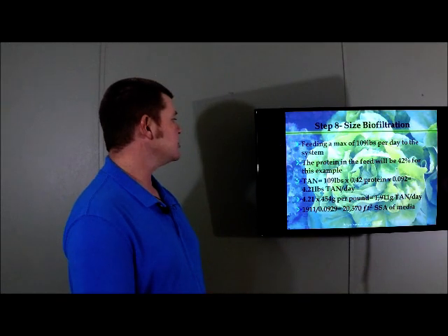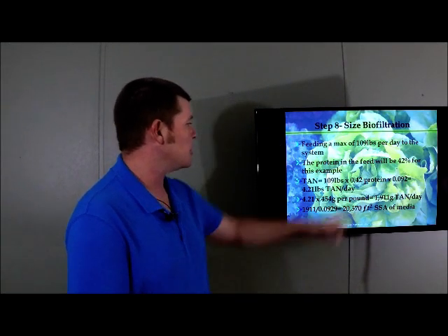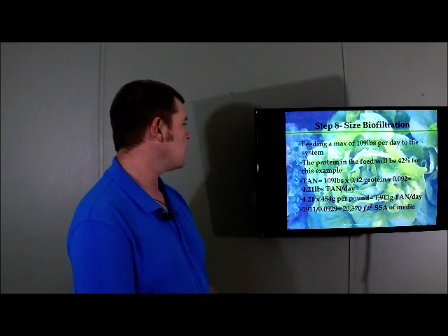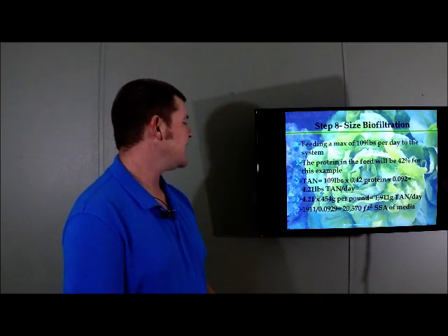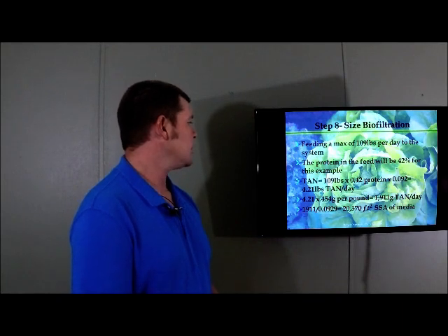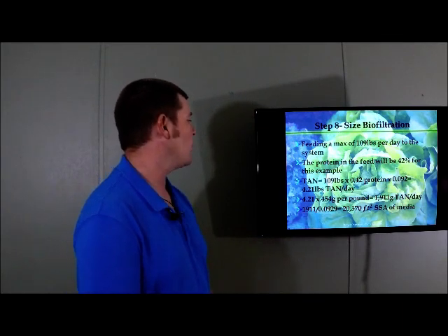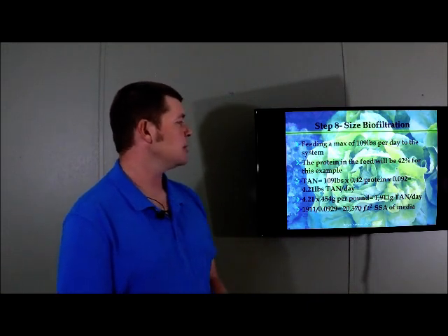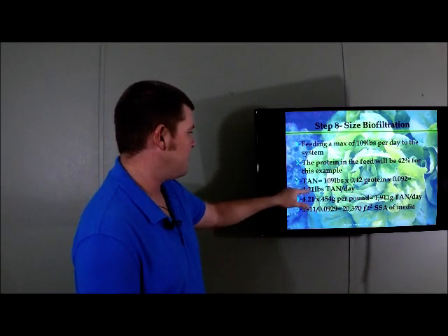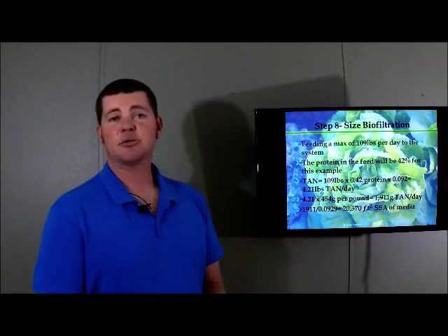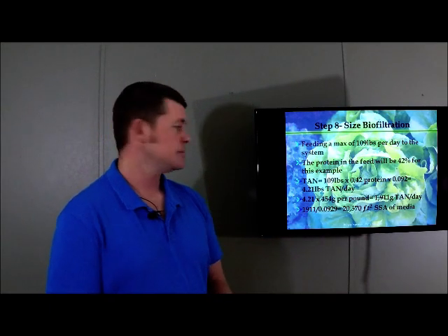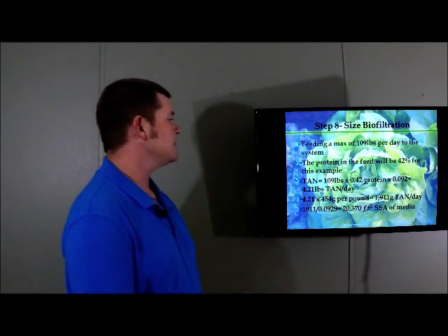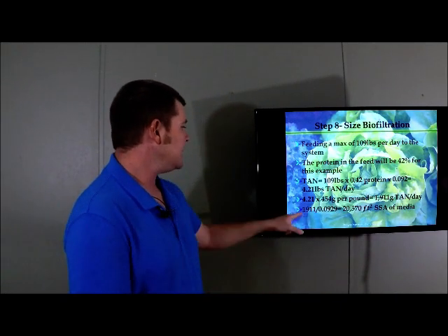The total ammonia nitrogen is 109 pounds times the protein content, 42%, times 0.092, and that gives us 4.21 pounds of TAN per day. 4.21 times 454 grams per pound gives us 1,911 grams. So I just changed it from pounds to grams because we size our SSA off of grams, okay? Our media. So we have 1,911 grams of TAN per day.